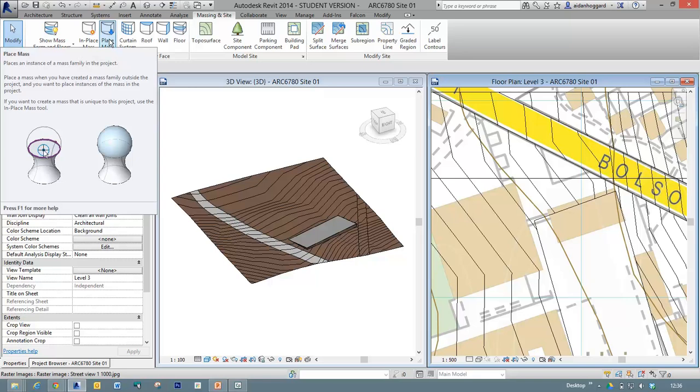Once you have a building and you know that level 4 means a certain floor in the building, then you can start to reference from that floor. Okay, so the building pad will change automatically according to the building level. No, not the way I've set it there. It will if I went into level 3 and changed level 3, then yes, everything that I've defined from level 3 will go with it. Yeah. Okay.